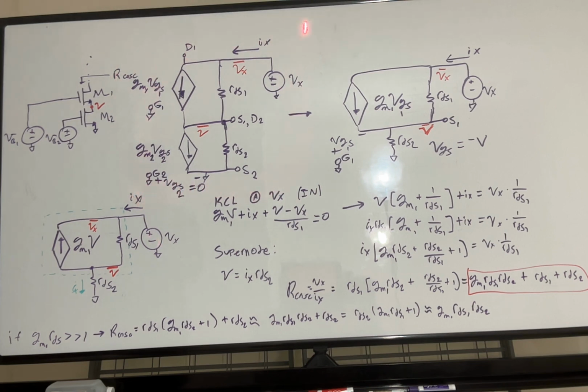And this is the unsimplified small signal model. We cut the circuit along our cut. We attach a test source of Vx and Ix. I've annotated the voltages here in red just to make it more clear. And the first thing that's immediately apparent is that VGS2, so this notation I have, when I put the 2 beneath the VGS, that's just VG2S2. So that's the voltage at gate 2 minus the voltage at source 2, right? And we'll notice that's 0 because they're both grounded, right? So since this is 0, this current source becomes an open circuit.